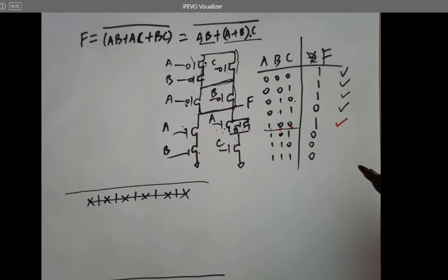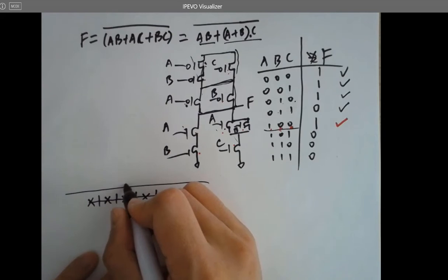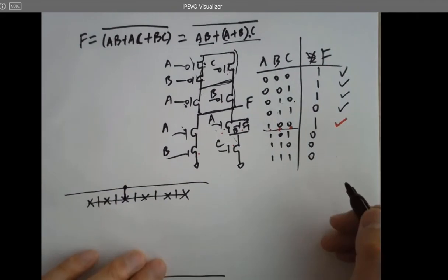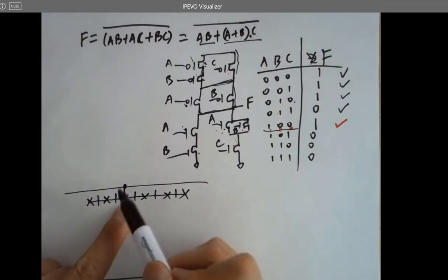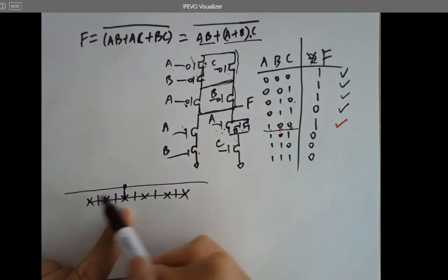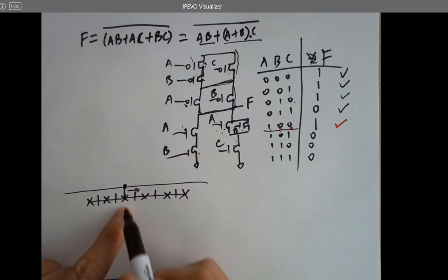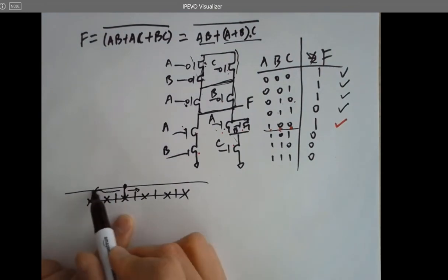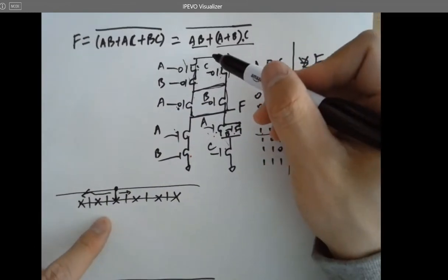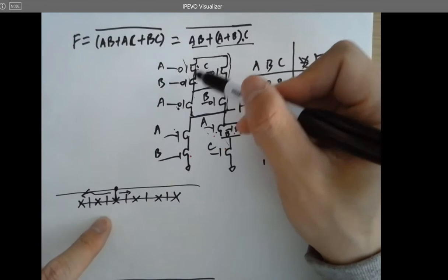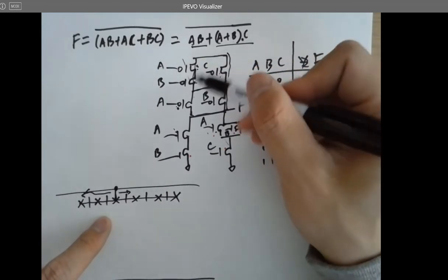2 in series, 1 in parallel. So if I draw a line from VD, introduce a signal to this transistor, to this P+, and I'm going to have these 2 in series, and on the right hand side I have another one in parallel with these 2 series PMOSes, right? So it's definitely implementing this structure. So 2 in series, 1 in parallel with these 2 series PMOSes.